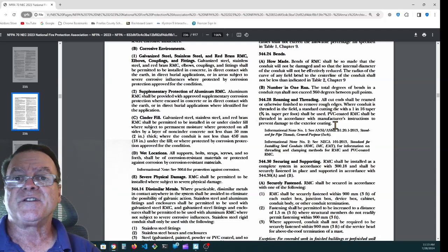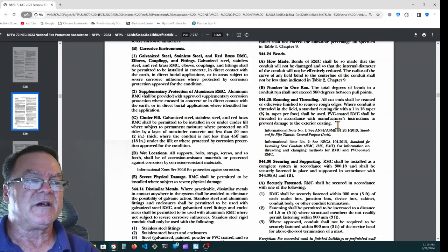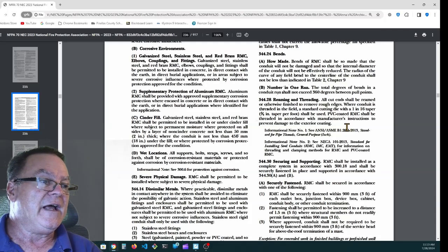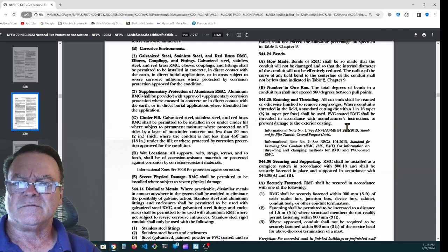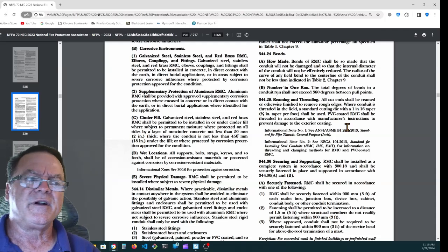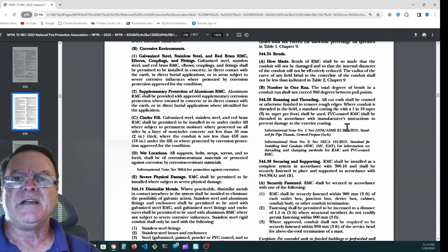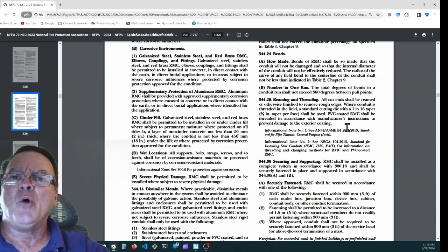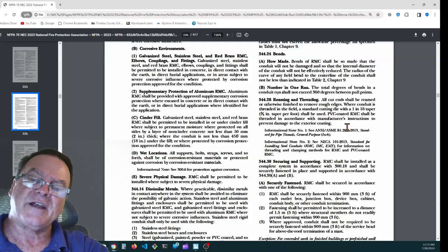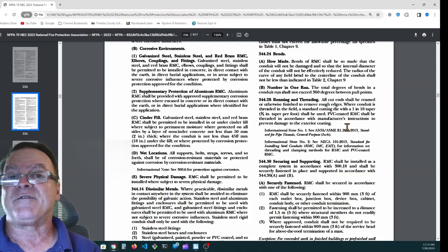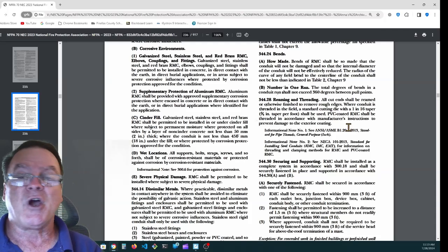You don't want to leave too much of the pipe exposed. You don't want it to be susceptible to corrosion in severe environments. And you don't want to leave that coating on when you thread because it gets clogged up in the threader, and sometimes it has a tendency to make the entire PVC coating slip on the pipe, it could come loose and actually start turning up separate from the rigid metal conduit that it's coating.